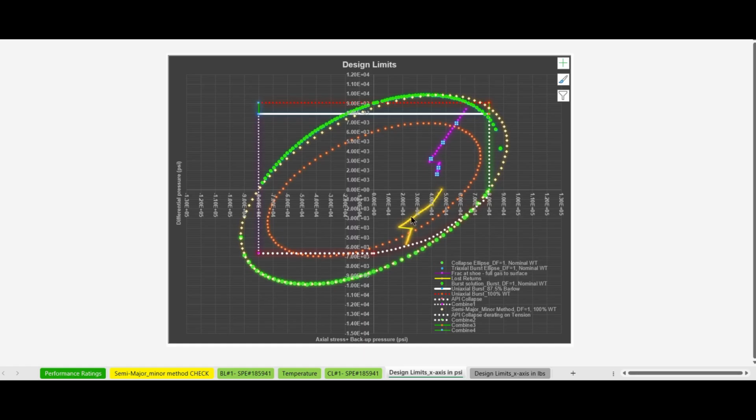For collapse, it is basically the burst pressure, and sorry, internal pressure. And as you remember, above 2,000 feet, it is zero internal pressure because of the loss returns. Then this straight line refers to your top of cement, where basically we followed an approach of a midpoint.